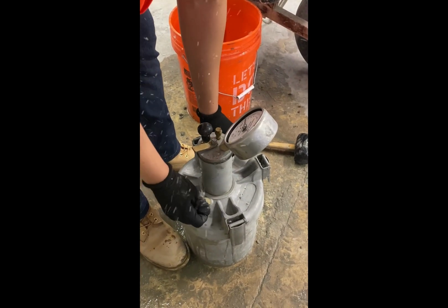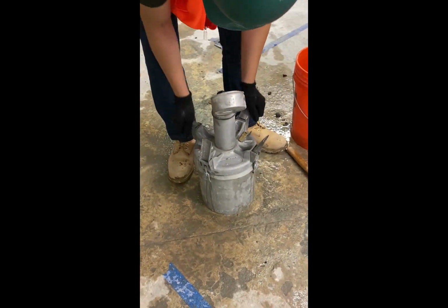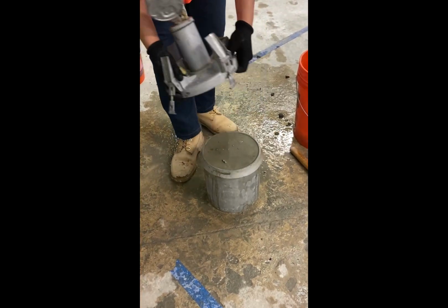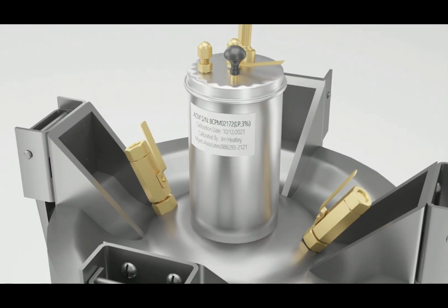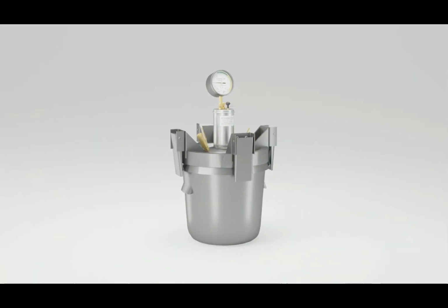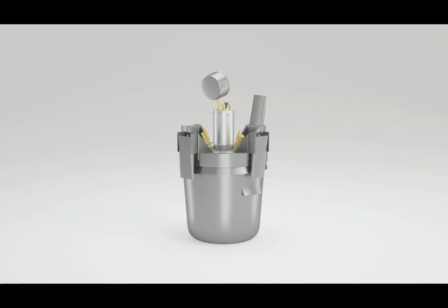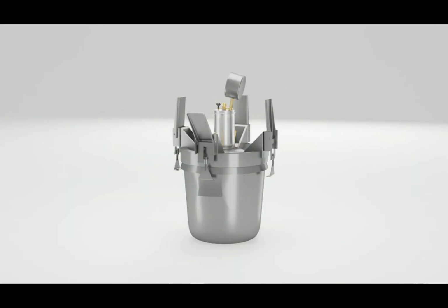Failure to close the main air valve before releasing the pressure from either the container or the air chamber will result in water being drawn into the air chamber, thus introducing error in subsequent measurements. In the event water enters the air chamber, it must be bled from the air chamber through the air bleeder valve, followed by several strokes of the pump to blow out the last traces of water. Release the pressure by opening both petcocks before removing the cover.